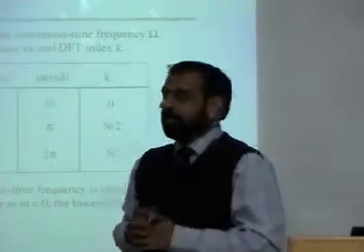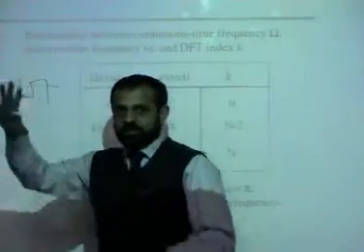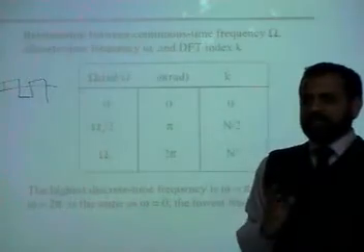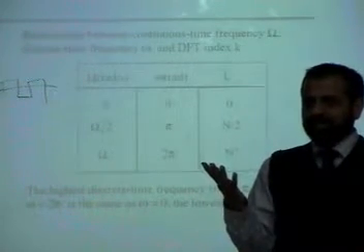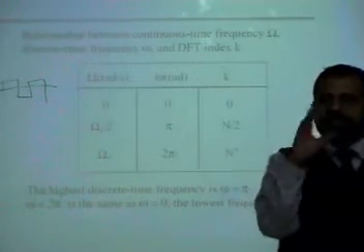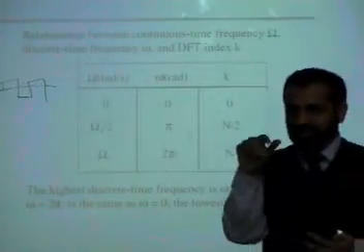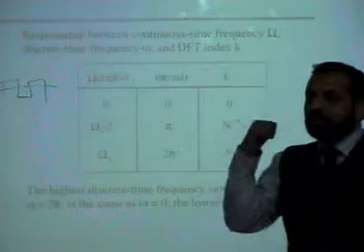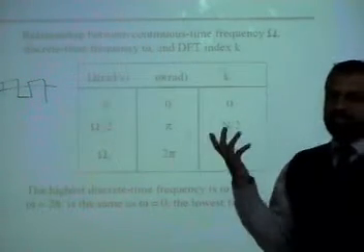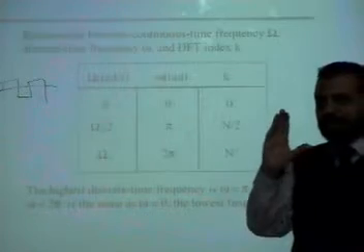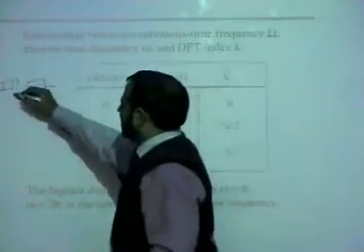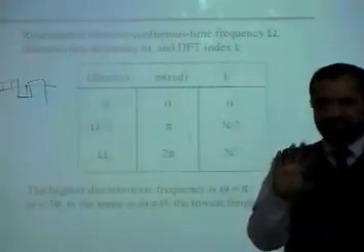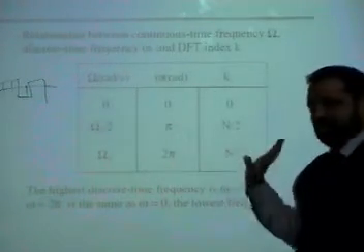How is it related to that? If you have a signal, you generate 1 and 0, 1 0 1 0 1 0. Worst case, let's say you say 1 kilobit per second. What is 1 kilobit per second? In 1 second a signal can change 1000 times. So you generate a worst case scenario, where it is always changing, 1 and 0 1 and 0 1. Plot its frequency response, just take its Fourier transform. And 1 kilohertz will be a frequency band, because it requires 2 samples. I think it will be almost equivalent to 1 kilohertz or 2 kilohertz, I don't remember, but it is related to that. Why?